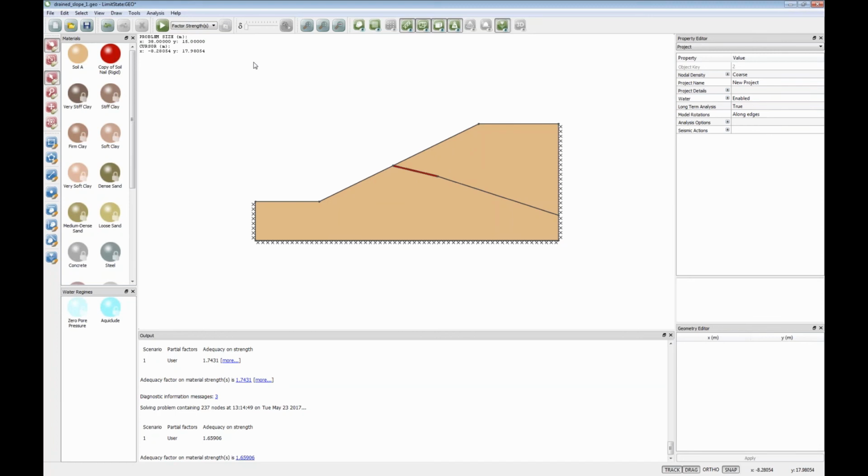I've got another question about the use of Eurocode partial factors for slope stability problems. So I think the general consensus is that slope stability should be solved using design approach 1 combination 2, because basically the driving force is generally the weight of the soil, and you can get into all sorts of issues working out where favourable and unfavourable loads are if you use design approach 1 combination 1. And I think for those people not using design approach 1, usually design approach 3, which is very similar to design approach 1 combination 2, is the recommended one for slopes.